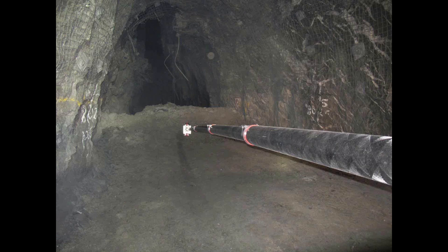Absolutely. So all of the surface comparison tools that are utilized for movement detection, settling, comparing thickness by actually coloring one triangulation from its distance to another that we utilize in the open pit tools, all of those translate directly into 8200 scans for underground. So we have used them to monitor shotcrete thickness and actually create colorized 3D reports with a legend. And you can definitely, once the scan is registered, comparing it to prior registered scans, you can check for settling or convergence as well.